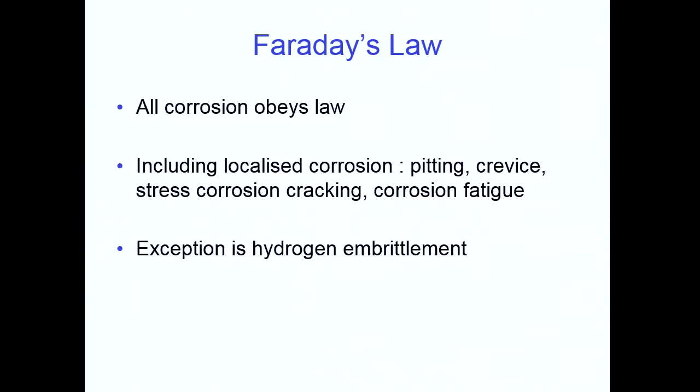So all these corrosion processes that we're thinking about are all anodic processes. So the structure is at a corrosion potential, some anodic potential. Whereas in the case of hydrogen embrittlement, quite often the structure is at a cathodic potential, and therefore it cannot be corroding.